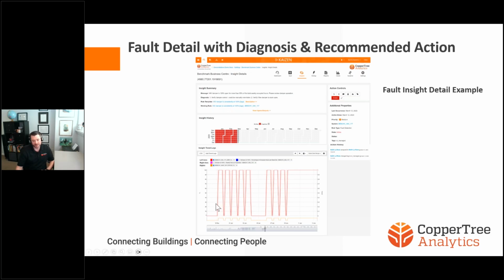I could see that this damper was behaving slightly bizarrely already. It was opening 100%, closing 0, 100, 0, 100, 0. Eventually it kind of gave up. It just is open at 100% according to the data here. Very simple example, but just to highlight what FDD is doing.